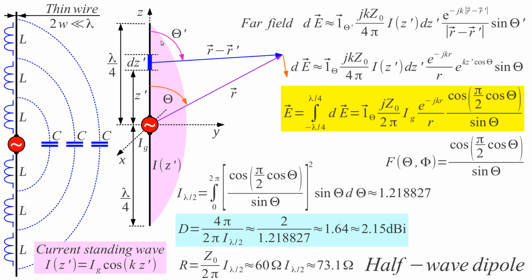I could make this antenna a little bit longer, say one wavelength, which still provides useful data with much higher radiation resistance, but longer than one wavelength, the radiation pattern of such an antenna is spoiled. The radiation pattern gets many very disturbing side lobes, so we usually don't build dipoles longer than one wavelength. Half a wavelength is the most typical example.